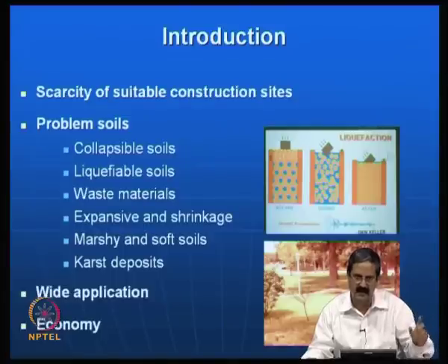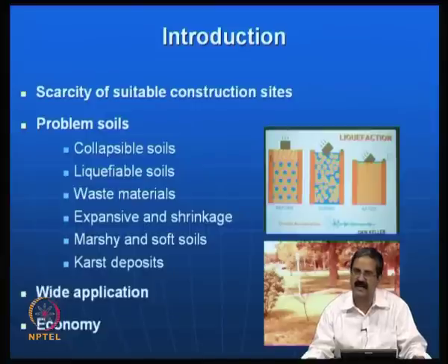So, this extreme range of water contents in the case of expansive soils causes significant expansion and also significant shrinkage, leading to a lot of volume changes, and because of this you have many problems like distress in foundations, loss of contact, and many other things.